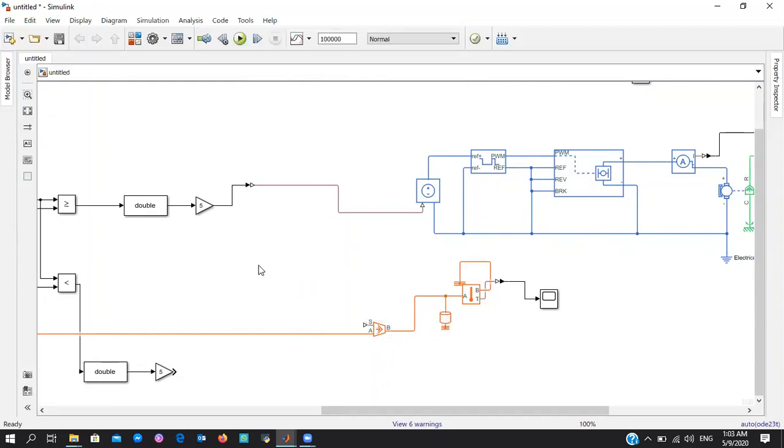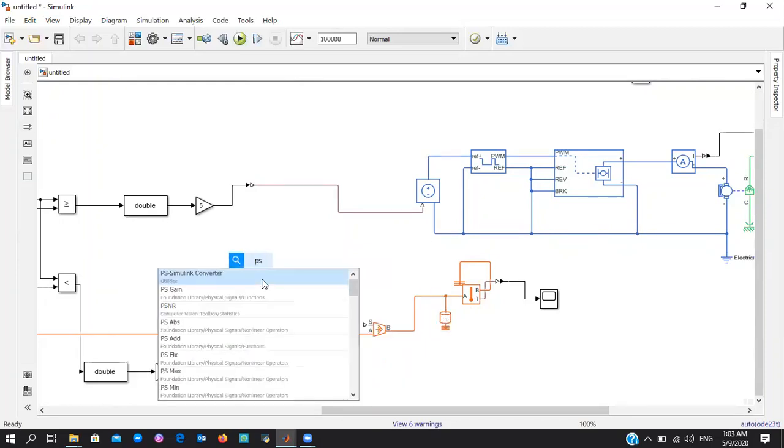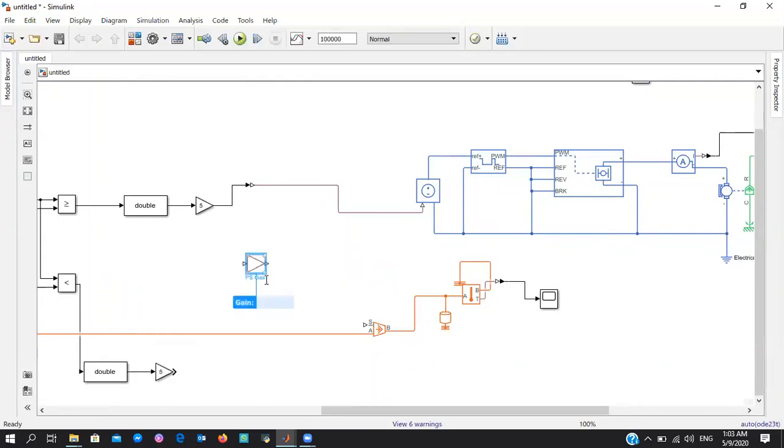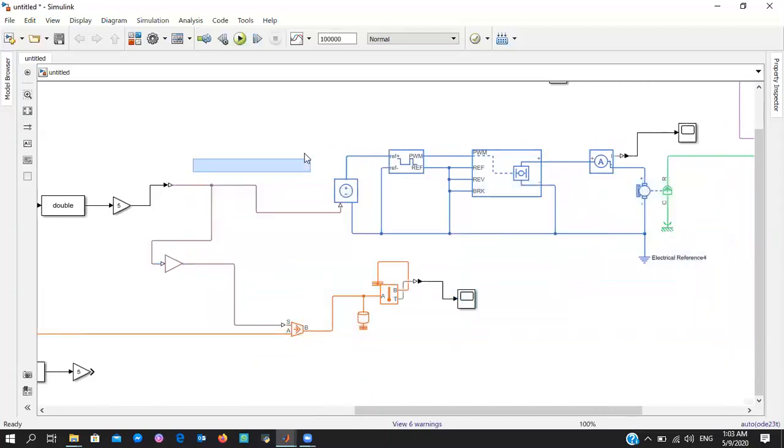Now I will need a physical gain. This gain will be 10. Why 10? We figured out while we're doing this project that 50 watts here would be just good. 5 from this one times 10 is 50. Now this is the cooling part. Now for the heating part, it's just the same with one minor change. So I'm gonna go ahead and copy all this stuff.